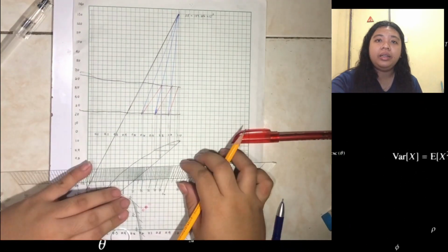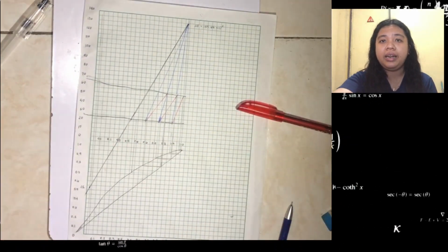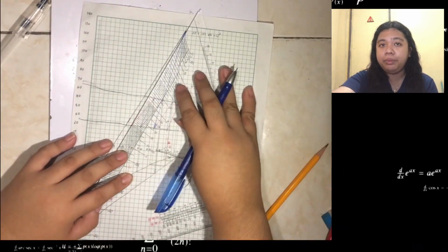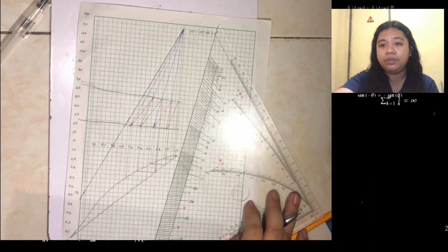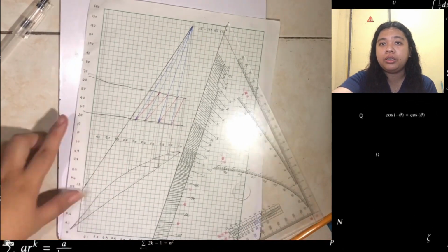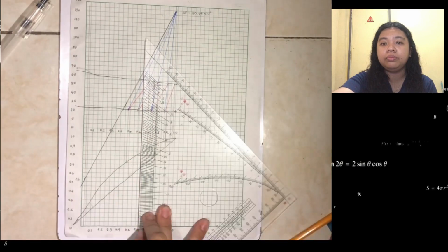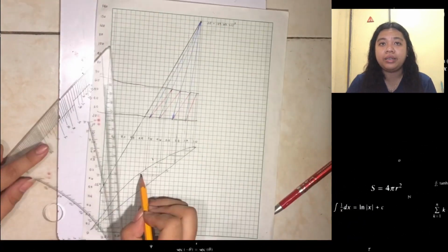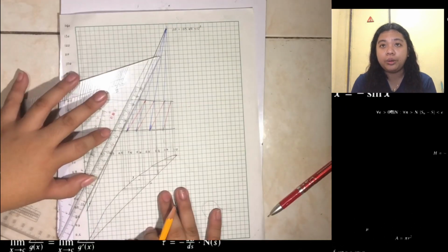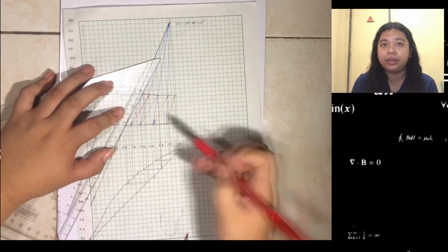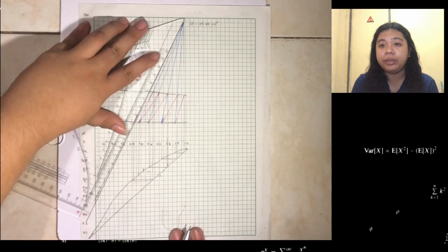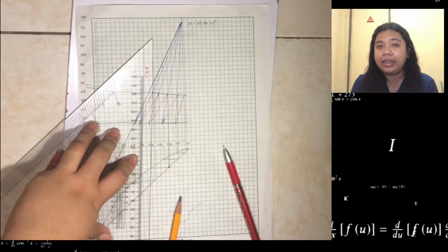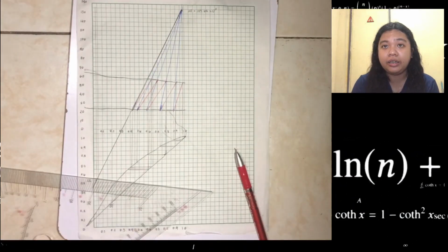From the saturated liquid point, or HL, create a line and extend it to the point delta E. The line that intersects the vapor will be our next HV point. Repeat the process till it passes through the feed point. Once it passes through the feed point, we will now use delta S for stripping. Create an operating line from delta S till it reaches the last HL point and extend it to HV.